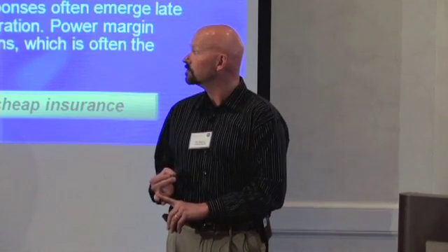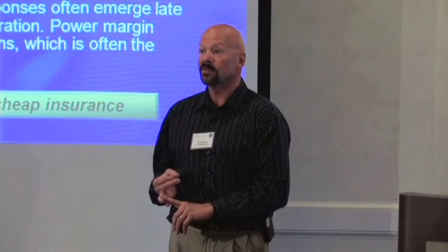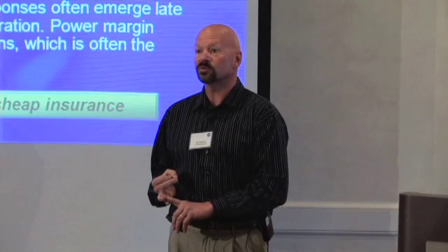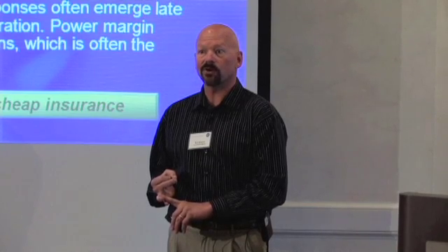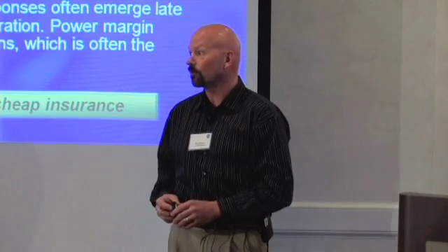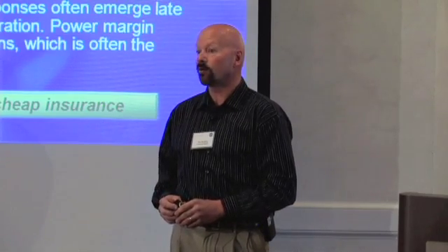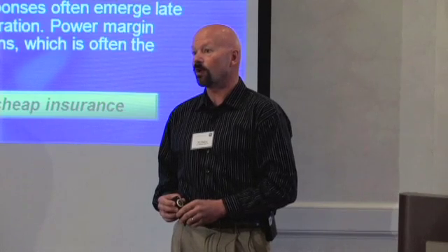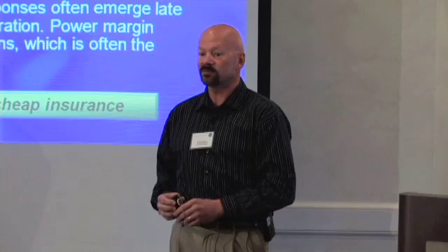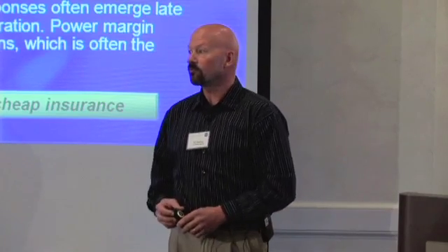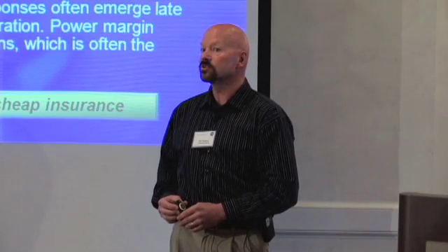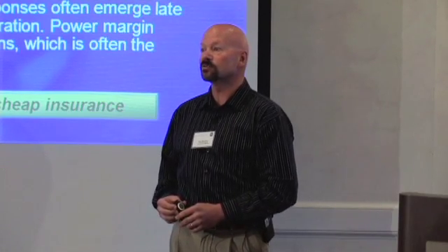You've got to do the things that it needs to do autonomously, and the solutions to those can only be done with the software and the sequences, not with the hardware, because that's been committed and that's already integrated, sitting on the clean room floor. And a lot of times power is the only way that you're going to solve that problem. Well, okay, I might have to go through a reset. I might have to do a sun search slew. Do I have the battery power? Can I recharge my batteries? And those things you don't learn until it's way too late to fix it with hardware.